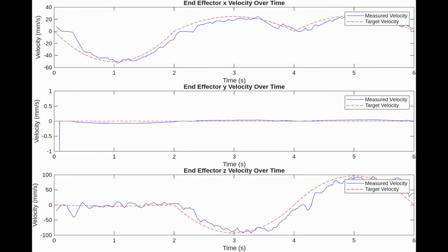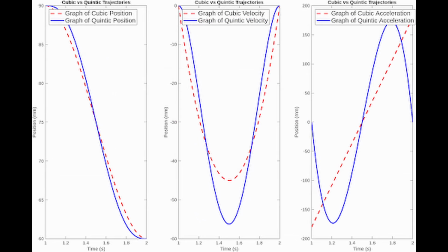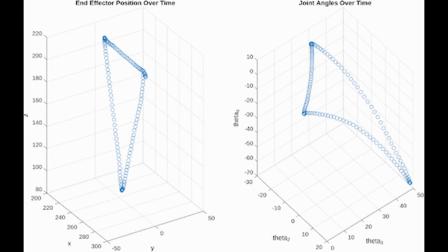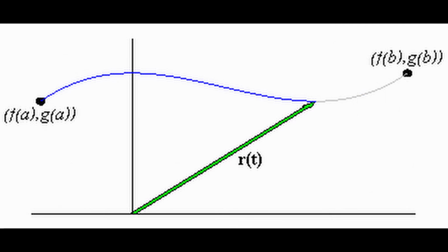Evaluating these equations multiple times a second and continuously changing the pose, which is targeted by our inverse kinematics, moves the arm in the desired path. By doing this, we can avoid sudden starts and stops, ensuring smooth movement and reducing excessive stress on our motors, while also preventing overshoot. Using this concept, we created additional trajectory planning methods.